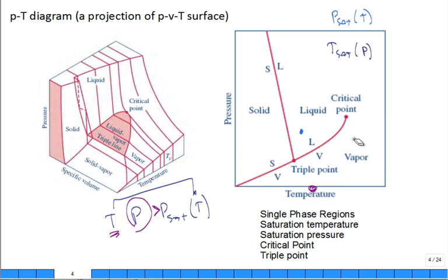maybe I'll erase this and show it on the diagram. Take this temperature. I know maybe the pressure is right here. I get the saturation pressure. There's P sat. There's the physical pressure, P, and P is greater than P sat. Isn't that what I said in equations? I'm in the liquid phase. Or what happens if it comes back and says the pressure is not greater, it's less? I'm in the vapor phase. See how you kind of test that?